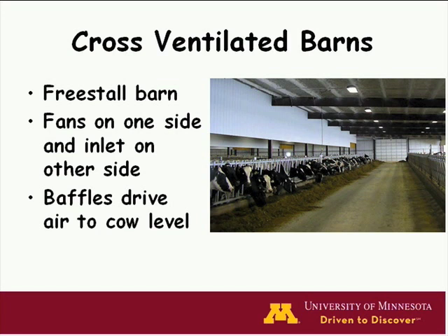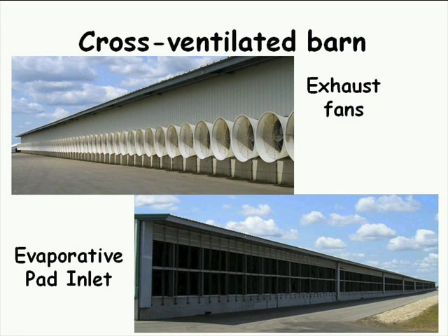And these cross-ventilated barns in the dairy have baffles, which we have here. Here in this area is a baffle that's hanging down over the free stalls, and this drives the air down into the freestall areas so that air doesn't just flow over the top and does not provide as much cooling there. Now these baffles do contribute to the static pressure drop, but they are managed.